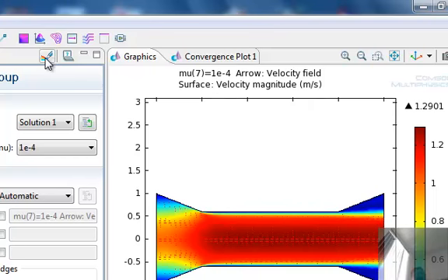It shouldn't. It shouldn't, because the flow should become turbulent and numerically it should become unstable. When I was testing it in my office, it did give me a non-converged result when I had a viscosity of 0.001 already. But I think the grid may be too coarse in here. So there are a lot of numerical issues that one needs to worry about when you're comparing it and interpreting the results physically. This is a result that is correct in terms of satisfying the Navier-Stokes equation. There is no doubt about it. It solves a two-dimensional Navier-Stokes equation, and this velocity field will satisfy that.